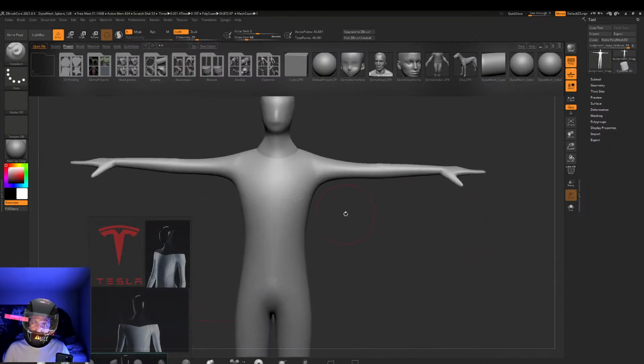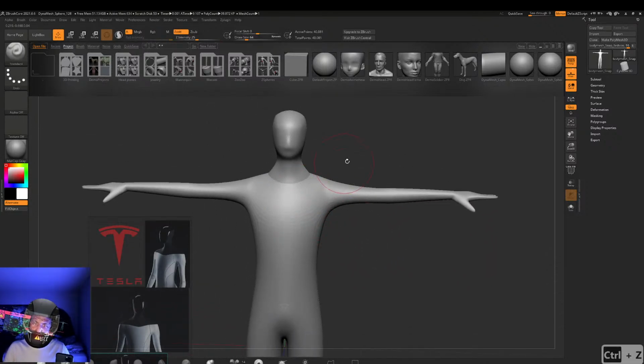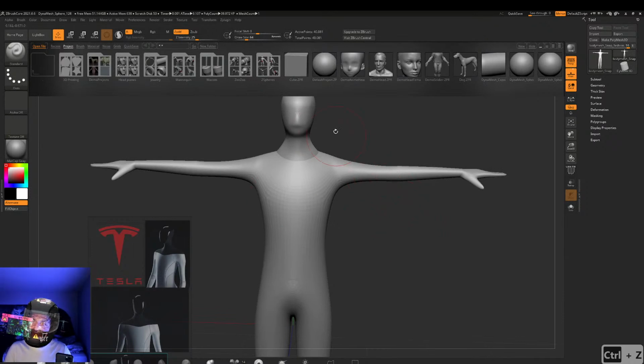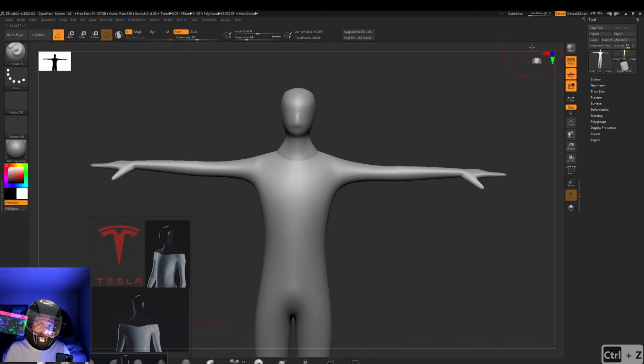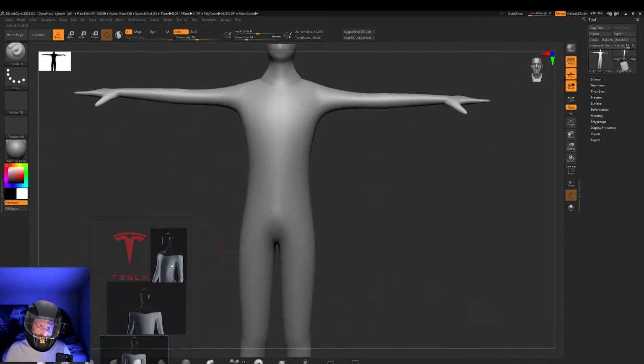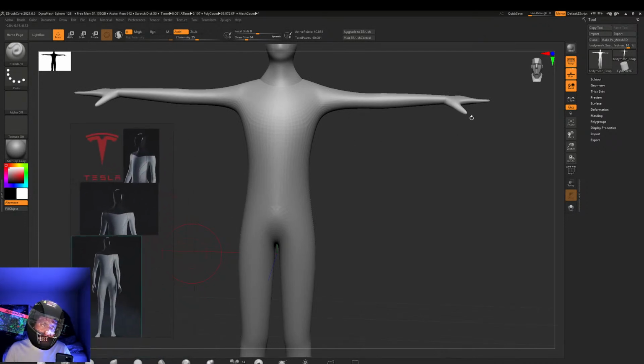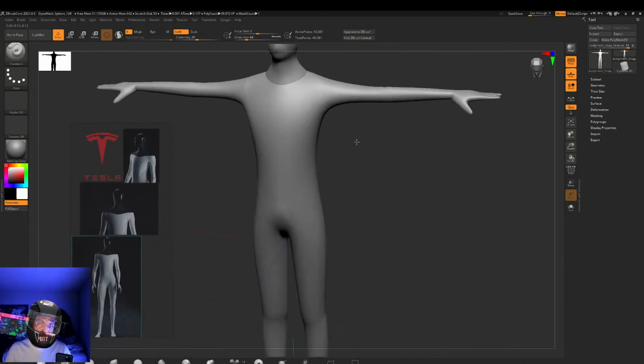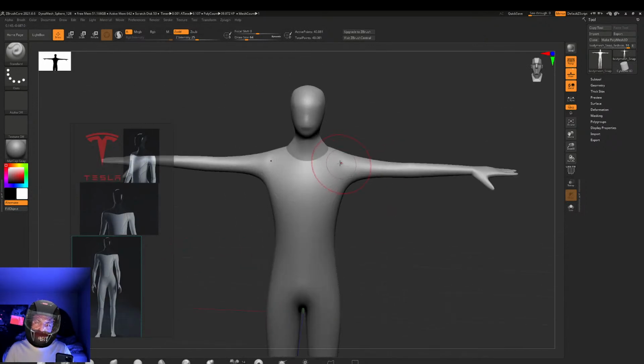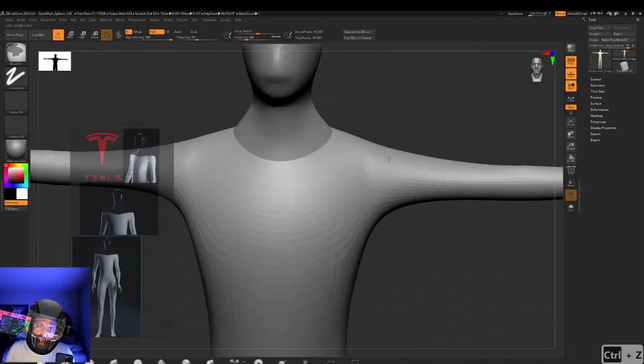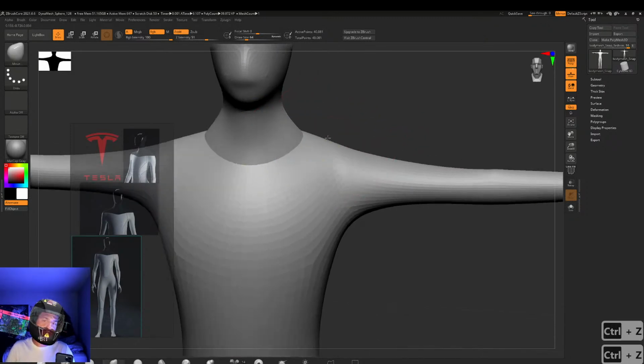which has a lot of power. So first thing I want to do is maybe Dynamesh this all together. So I'm going to hide that top bar. Dynamesh is a technique that kind of just blends all the geometries together as one mesh. Because right now it's still interpolating it as separate meshes. Oh, actually, it looks like it's kind of working. If I go to the move brush, let's see what happens. Okay, it looks like it is combining all the meshes together. So I guess we are okay.